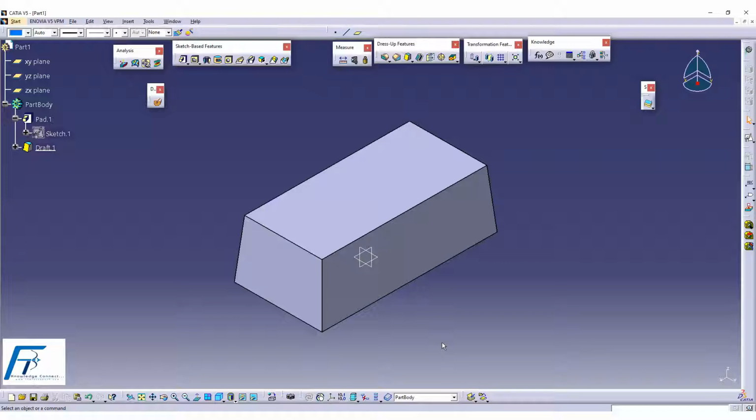So now moving on, now we know draft simple, we need to give these components. The draft for a plastic component is not much less than 4 to 5 degrees, maximum is 5 degrees. Metal casting can go a bit higher. So there is a concept where any plastic component, be it any trims of an automotive or interiors of an aircraft, is made up of plastics, where the draft angle is a must because of its molding capabilities. Unless you give the molding draft angle, you will have those challenges.